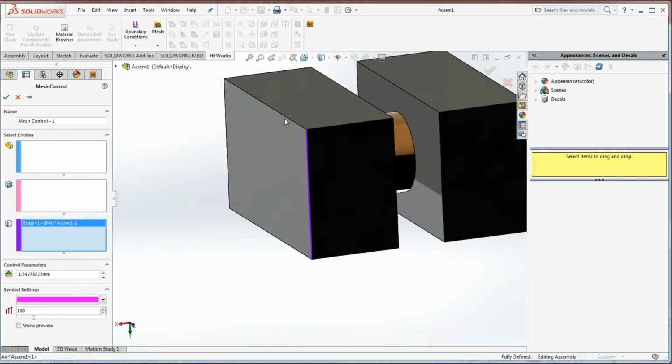Give me a finer mesh. This way, I can make sure that I will have more elements in, for example, sharp edges where there is a possibility of the singularity of the field or anything, and where there is smoothness and I don't need so many elements, I will leave it coarse so I can have a faster computation.